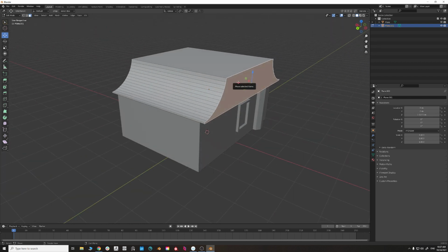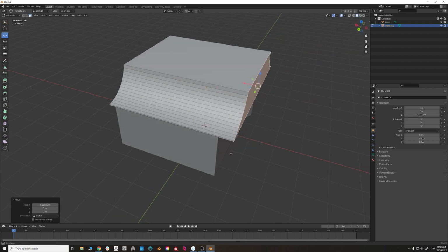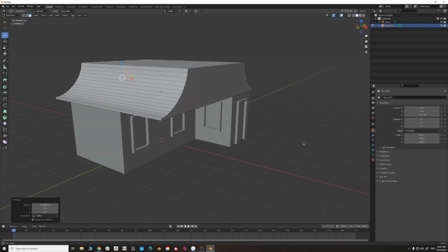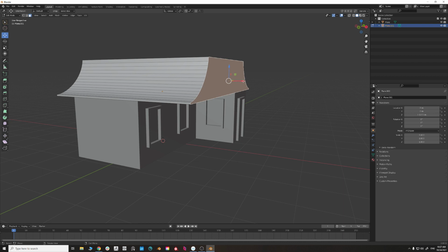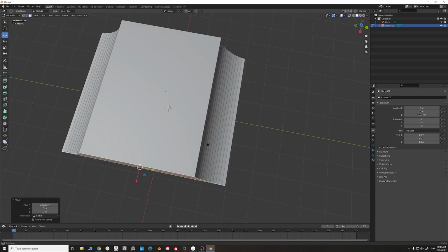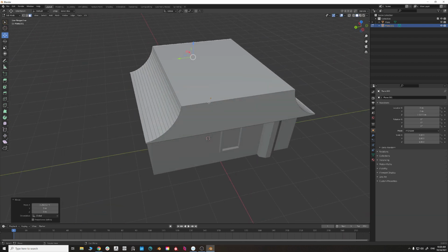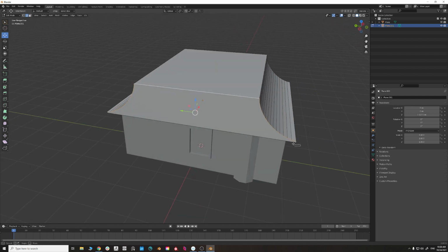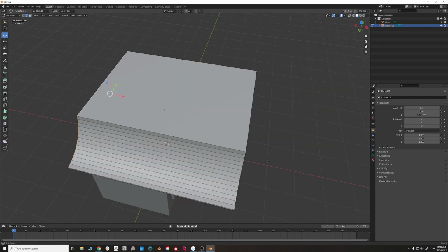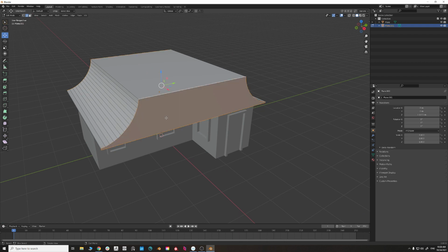Push this out as well. Push this even a bit further. And what we want to have here is also have a slant across all of these. So I'm going to go to edges again. I'm going to remove the bottom one and these ones here from the side from the selection. And while holding Shift, I'm going to select these and again remove these from selection.